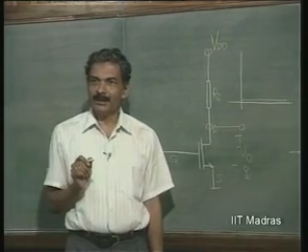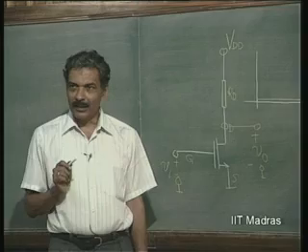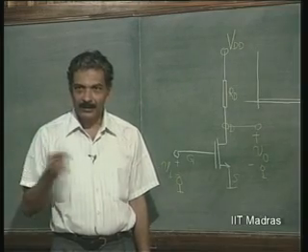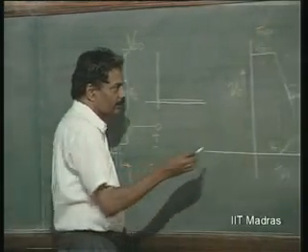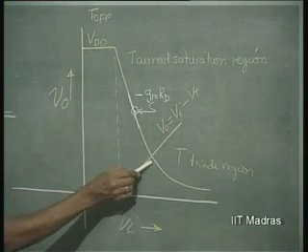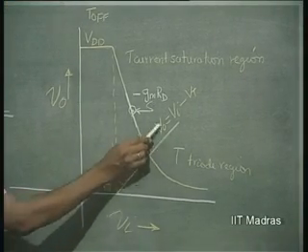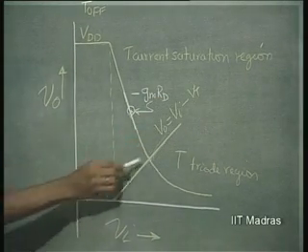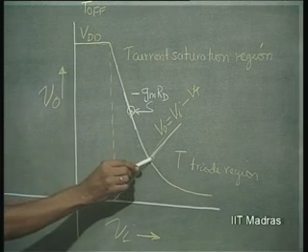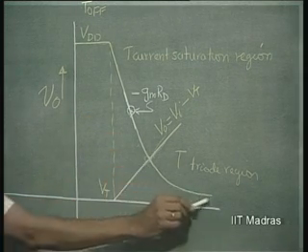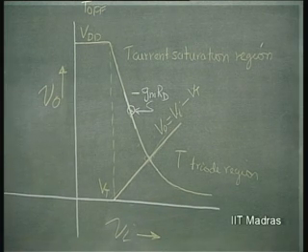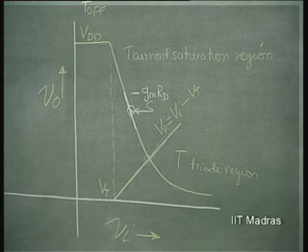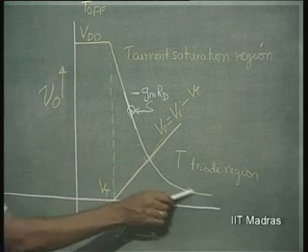Same thing happens in the case of a bipolar junction transistor. As current is increased, Gm is increased. So, at this particular point, when V0 or Vds becomes equal to Vi, which is Vgs minus Vt, that is the line separating this current saturation region from the triode region. The transistor enters the triode region. The equation to be used is Ids equal to 2k into Vi minus Vt into V0 minus V0 squared by 2. That is for Ids, and this relationship is followed.